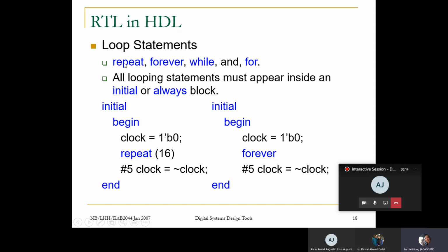But why does Verilog include the initial statement if it cannot be translated into hardware? The main reason is it is used for test bench, for simulation purposes, for managing signals. Signals you want to change only one time, that you feed into the design you want to test. So the initial statement is only used in test bench, right? When you write a test bench, this is the time to use your initial statement. When you write the design, do not use initial statement.